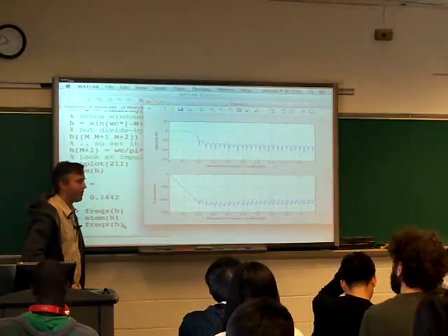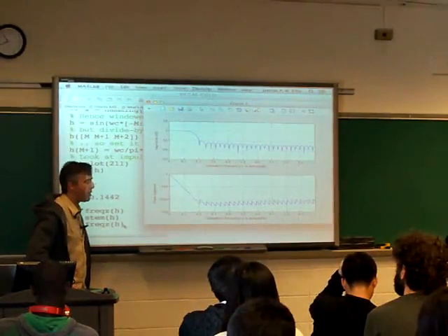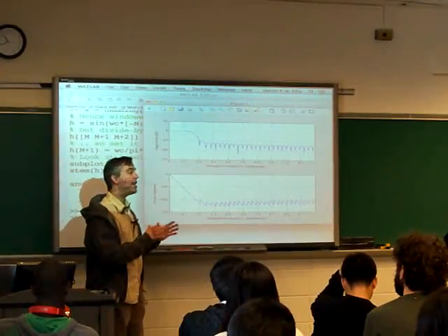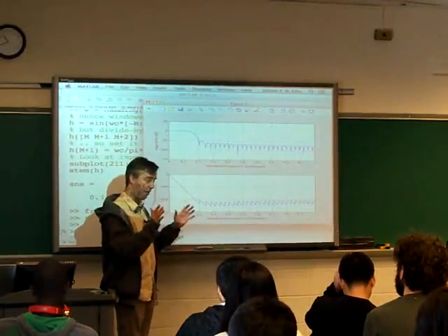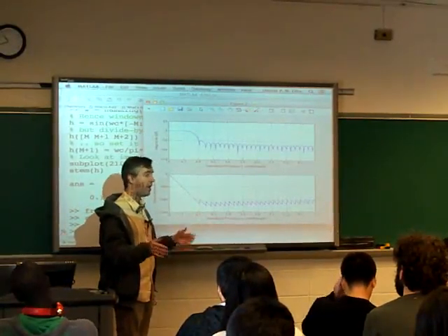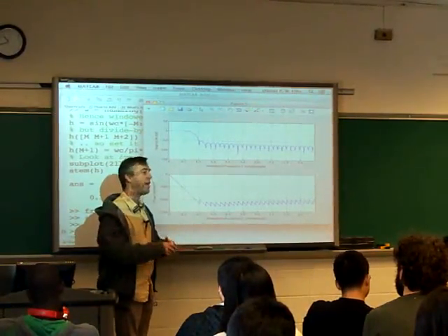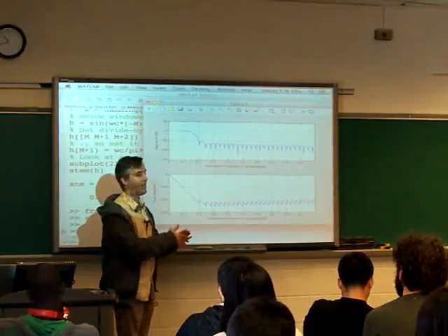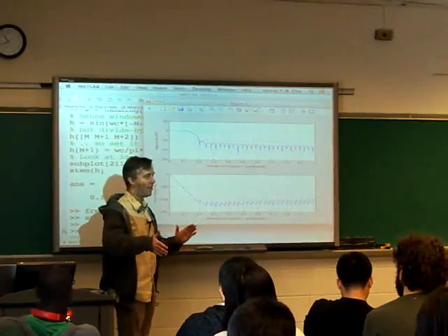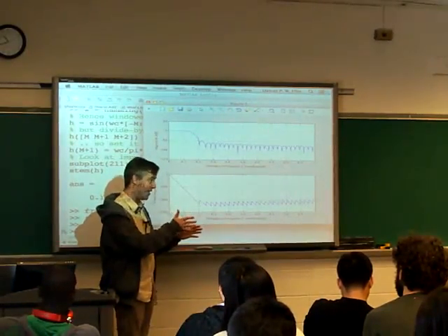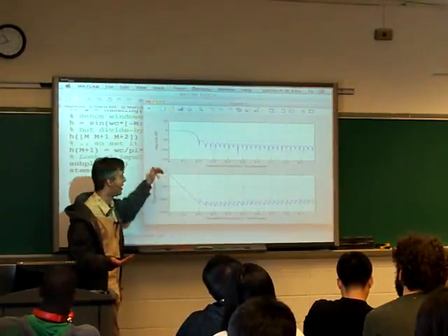Did we deliberately do something to make it a linear phase response? Why is it linear phase response? We started out with the ideal zero phase impulse response, the IDTFT of the zero phase thing, which was the sinc function. We then windowed it and kept it symmetric, but then we had this 65-point filter, which MATLAB interprets as starting at 0. So it says, oh, okay, you want a 65-point filter, which is going to delay everything by 33 points. If we'd said, no, we meant a 65-point filter centered at 0, then it would have been a zero phase response. But because MATLAB assumes it's a causal filter, it shows us the delay.